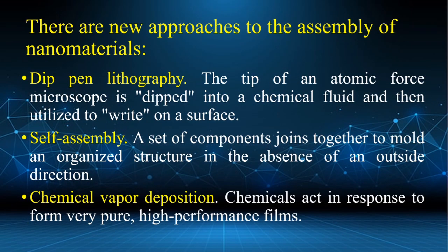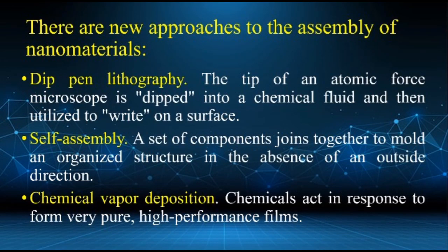There are new approaches to the assembly of nanomaterials based on the application of principles of top-down and bottom-up fabrication. This includes the dip pen lithography. It is a method in which the tip of an atomic force microscope is dipped into chemical fluid and then utilized to write on a surface like an old-fashioned ink pen onto paper. Next is the self-assembly. It depicts an approach wherein a set of components join together to mold an organized structure in the absence of an outside direction.